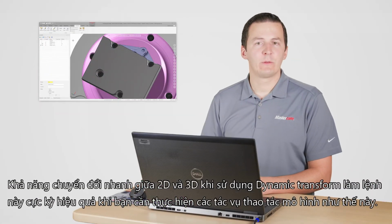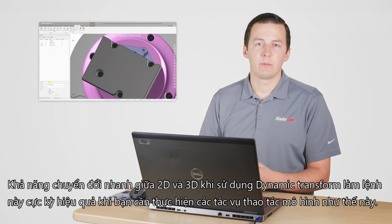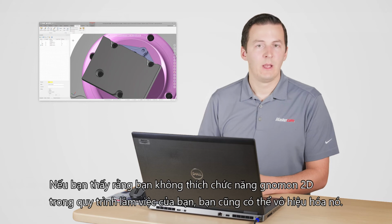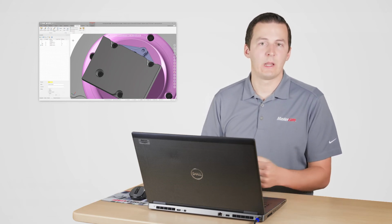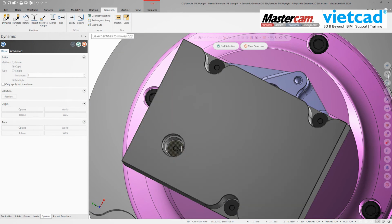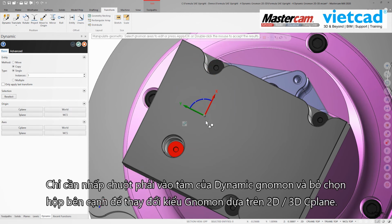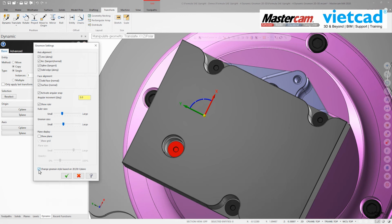Being able to quickly switch between 2D and 3D when using Dynamic Transform makes it extremely efficient when you need to perform model manipulation tasks like this. If you find that you don't like 2D Gnomon functionality in your workflow, you can disable it as well. Simply right-click on the center of the Dynamic Gnomon and uncheck the box next to Change Gnomon Style based on 2D, 3D C-plane.